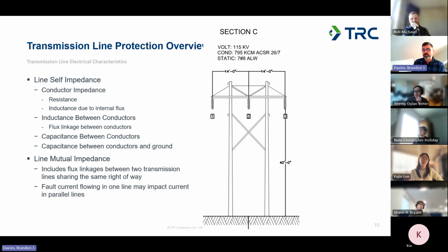So you may have gone over this in some of your other power classes, but basically, for your transmission line, you can do a bunch of calculations to take the physical relationship between your conductors: the spacing between your adjacent conductors and each pair of conductors, the spacing between the conductors themselves and ground, how much the conductors sag, so halfway down the line, or between two structures, how low does that conductor go to ground, and the spacing between your conductors and the ground or static wire.